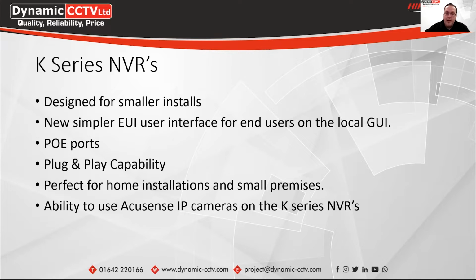The NVR itself would then activate that camera with the admin password and also give it an IP address within the 192.168.254.1 and above IP range. The recorder's physical PoE port on the back would be 254.1 for the recorder's address, and the cameras would be 254.2, 3, 4, and onwards when they're plugged straight in the PoE ports.